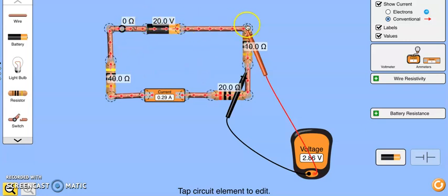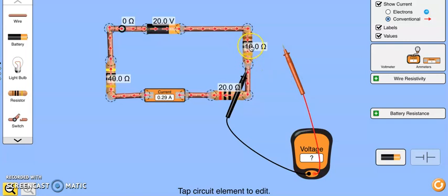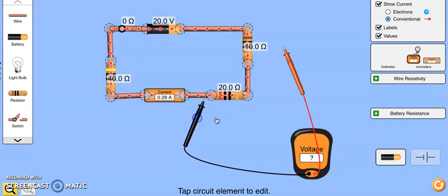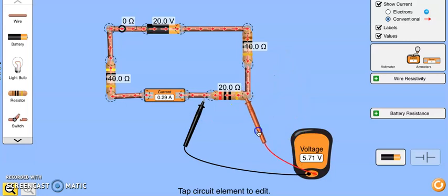So what happens is when we put resistors in series, each resistor acts like a small drop of the overall whole that comes from the battery. So we can understand now why Ohm's law actually does apply and gives the same current. The 10 ohm has a small resistance, but also has a small potential across it. So if I take that small potential divided by a small resistance, I get the same value as if I have a bigger potential divided by a bigger resistance. And it will be the same.